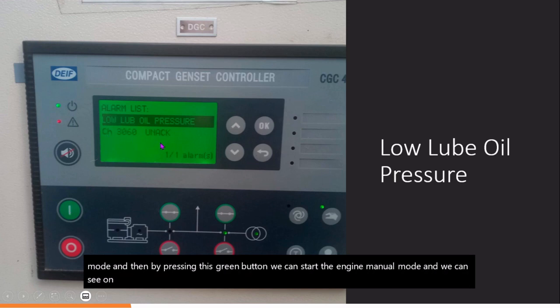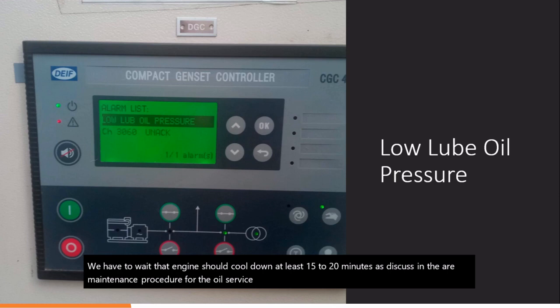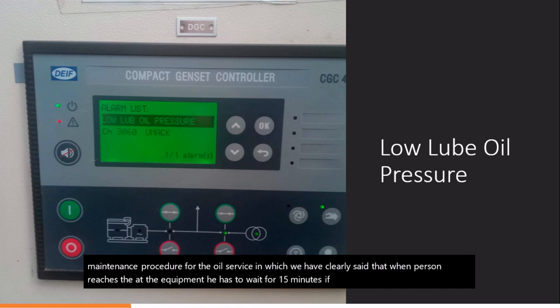We can see on the display what the lube oil pressure is, and before doing all these things we have to thoroughly examine inside the engine. We have to wait for the engine to cool down, at least 15 to 20 minutes, as discussed in our maintenance procedure for the oil service, in which we clearly said that when the person reaches the equipment, he has to wait for 15 minutes. If the engine is still running, it has to be cooled down.